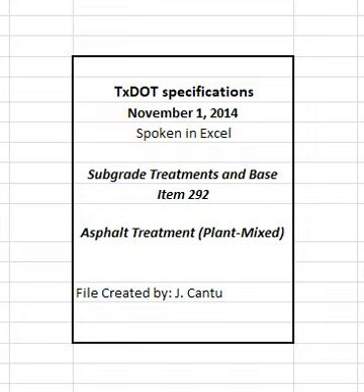Immediately after obtaining the cores, dry the core holes and tack the sides and bottom. Fill the hole with the same type of mixture and properly compact the mixture. Other methods of repairing the core holes are allowed when approved. Trim the cores, if necessary, and deliver them to the engineer within 1 working day following placement operations unless otherwise approved.